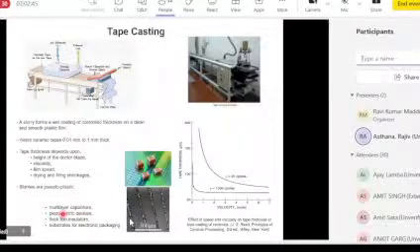That mixture serves as the feedstock. And that feedstock is put in the barrel of the injection molding machine. And you heat the mixture until the polymer melts. You go over the glass transition temperature of the polymer. So only the polymer melts in the barrel of the injection molding machine. The powders remain solid. So now you have created liquid polymer with fine powders of ceramic or metal suspended in it. You injection mold it in a water-cooled die to create a green part.